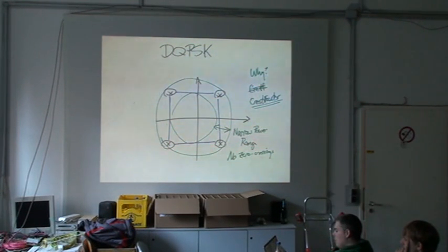It doesn't matter what the average is. The power amplifier has to accommodate the peak instantaneous power that your signal can generate, which means your amplifier is going to be drawing that much power all the time, no matter how much power you're transmitting at any given moment.